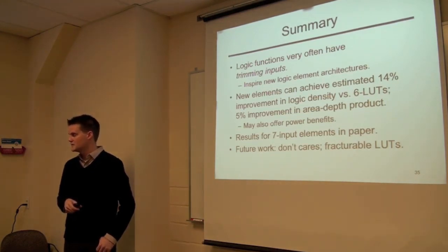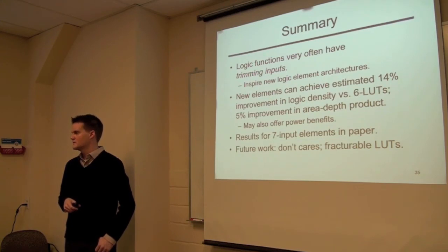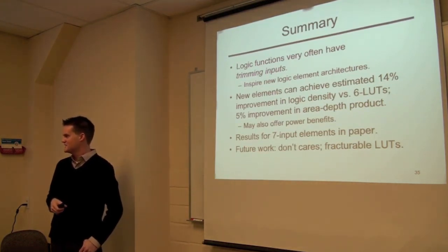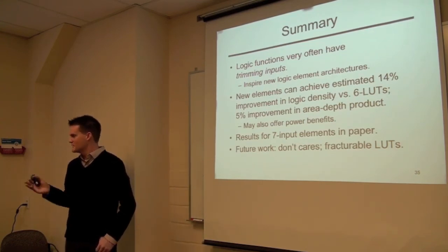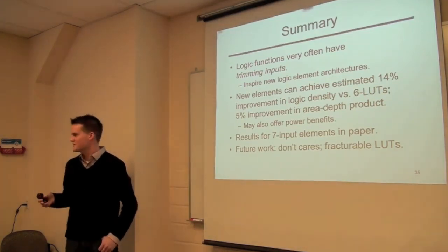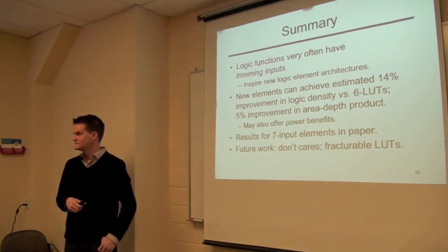Indeed. You could combine the two concepts, but the answer is not obvious what happens when you compete against a fracturable LUT, since it was trying to reuse the circuitry and you tried to get rid of the circuitry. I'd guess you'll probably have less gains from the fracturable LUTs when you combine both. If you had two 5-LUTs inside a 6-LUT versus now a 5-LUT and a 4-LUT, you reduce the amount of unused circuitry. The gains might add up to more than just fracturable LUTs alone, though, I don't know. I think it's interesting, because there will be an interplay. Sure, yeah.